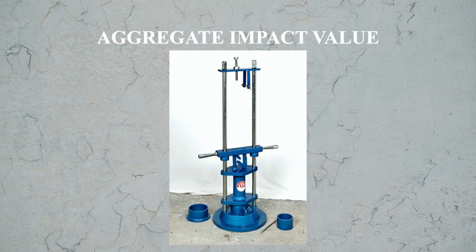So here you see the impact load machine. In this machine there is a hammer, which you see across the equipment, and this hammer is lifted and then dropped. This is done 15 times and the height of drop is 380 mm, as I told you earlier. So this load is dropped from this height of 380 mm 15 times on the sample, giving impact on the sample.